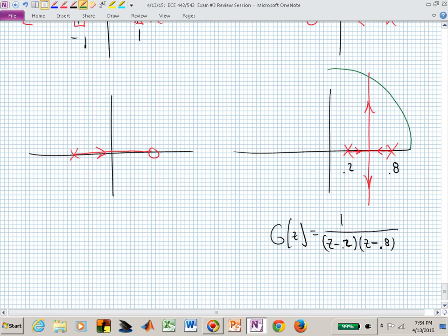I'm just going to draw a fourth of a circle, and then you won't know that my other 3/4 is really pretty bad. But I have a circle. Where that intersects that circle is the maximum you can crank up the gain to remain stable. Can you identify that point? It's really not that hard because you know the Pythagorean theorem. You know the radius of the unit circle is 1. You know the real part of that complex pole.